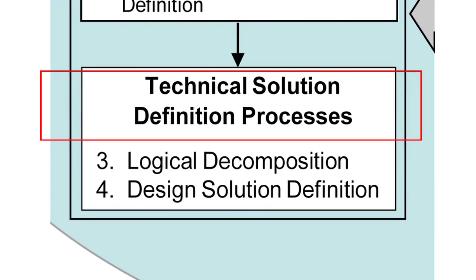So it's great to have a set of requirements, but that by itself isn't going to give you a spacecraft, right? You need to start to go off and do drawings and concept analysis of how do I take those requirements and turn them into a system. I don't yet know what kind of battery I'm going to buy to provide power, but I need a battery for the spacecraft, so I've got to do a design where I've included a battery. I'm going to need thrusters for the spacecraft to keep it in orbit, so I've got to define a propulsion system and look at how that might be designed. And so I'm starting to develop a concept of how it's going to look and what it's going to do in operations, and that's this next step of defining a technical solution.